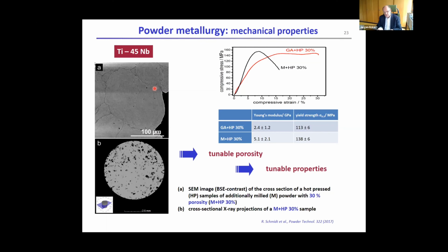And before, perhaps, or during the sintering, you may leach out this sodium chloride, and this gives you then some kind of porous structure, like it's shown on the lower left-hand side. And this, of course, means that besides having the phase right with intrinsic mechanical properties, you can adjust Young's modulus or the stiffness through different levels of porosity.